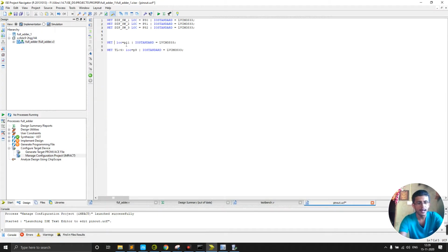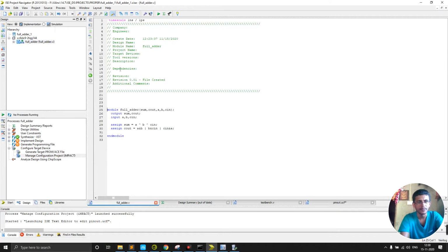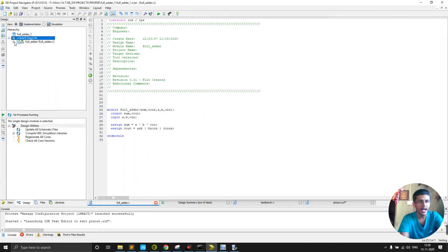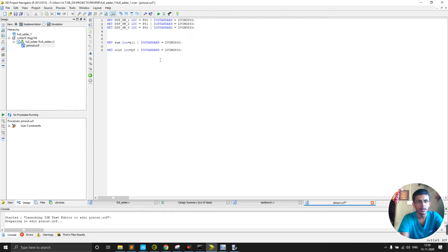So this is my sum, and this is my C out. Okay, C out. This name has to be the same as here. This is the sum and C out, and A, B and C in. Okay, not here. A, B and C in. So here this has to be A, this has to be B, and this has to be C in.